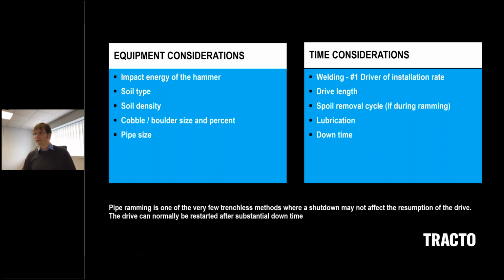Spoil removal needs to be planned carefully, and especially on longer pipe rams, we want to make a decision on whether lubrication of the pipe during the ramming process is required or not. And also we need to plan for potential downtime, though it has to be said that ramming is one of the few trenchless installation processes where even extended downtime may not necessarily lead to any problems.